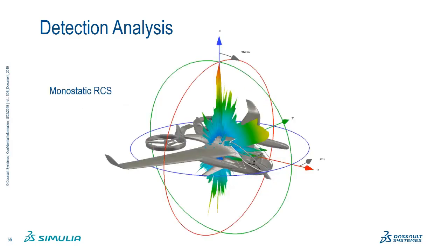The radar cross-section of an aircraft is a measure of its detectability. The size, materials, and shape all influence the radar cross-section, or RCS. Composites, especially non-conducting, will tend to reduce the RCS. Monostatic radar cross-section considers the scattering back towards the radar source. We can run a parameter sweep to solve for the RCS for different angles of incidence, and then output a 3D plot of the profile.